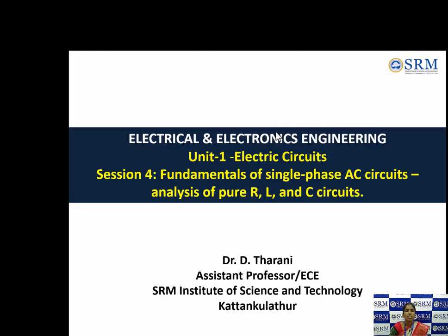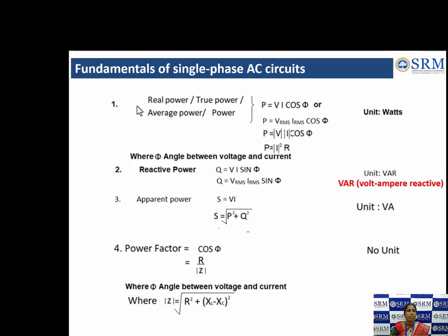In today's session, we are going to see the fundamentals of single-phase AC circuits and analysis of pure resistive, inductive and capacitive circuits and the combination of them. So coming to the AC circuit, we need to know different types of power and power factor. Actually, there will be real power, reactive power, and apparent power.